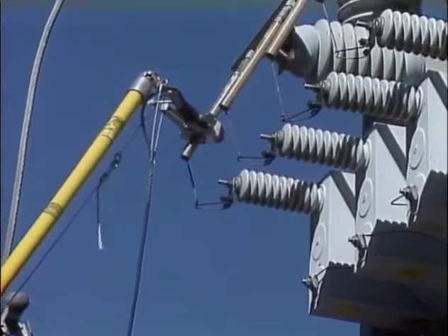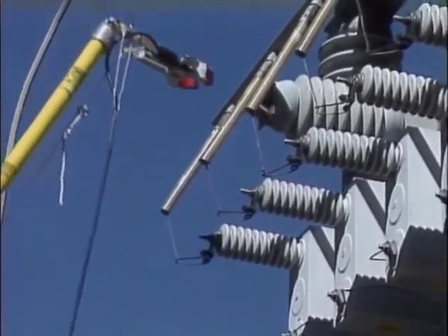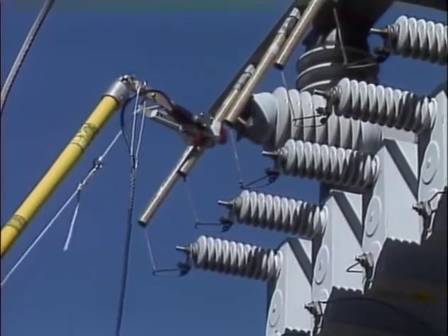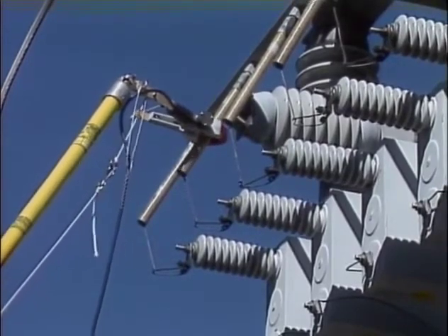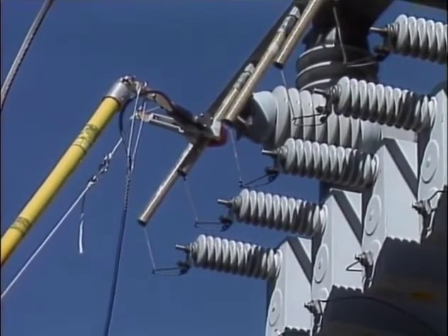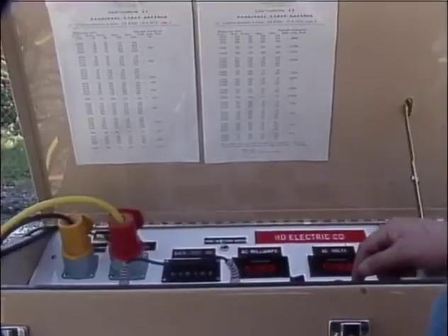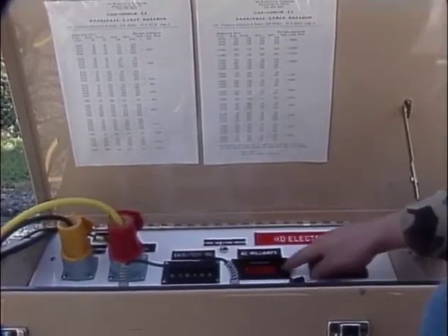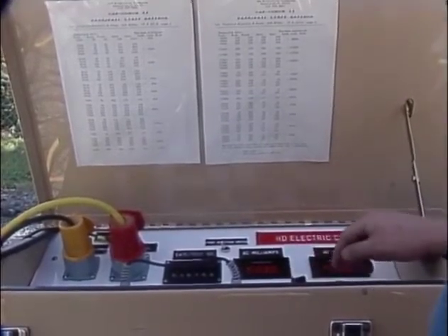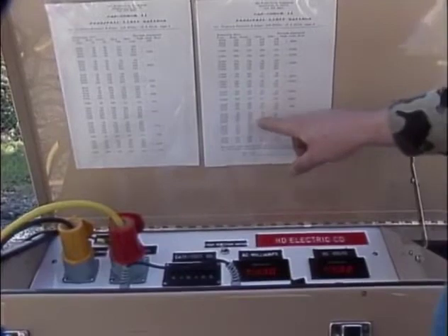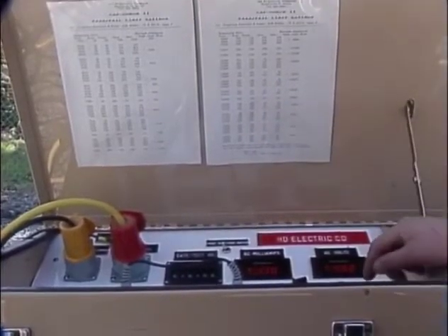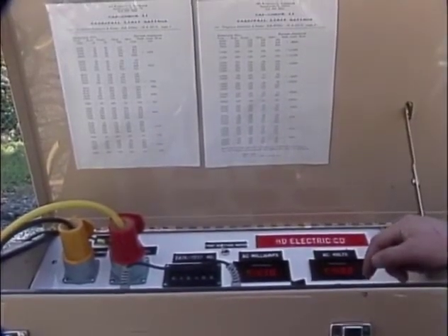The clamp probe is moved to the next capacitor, and the current drawn by that capacitor is measured and recorded. This is repeated until the current drawn by each capacitor in the section is measured and recorded. The current measured for each capacitor is compared with the acceptable range provided by the manufacturer. Any capacitor with a current reading either above or below the range should be replaced.